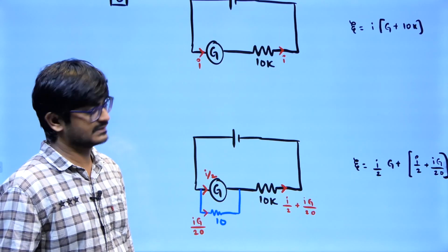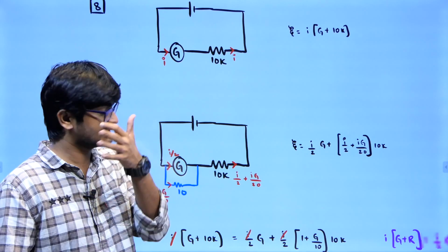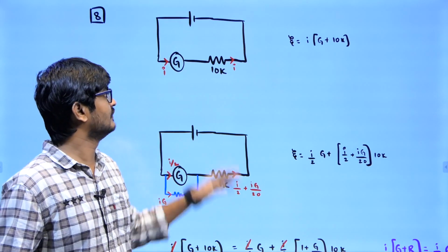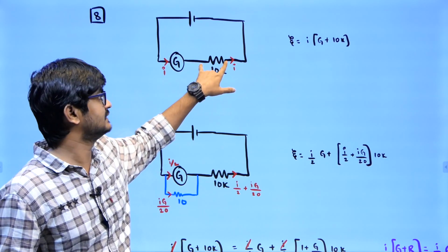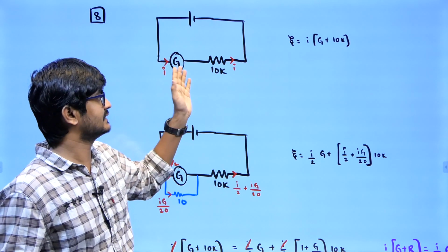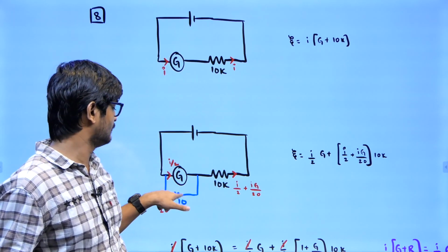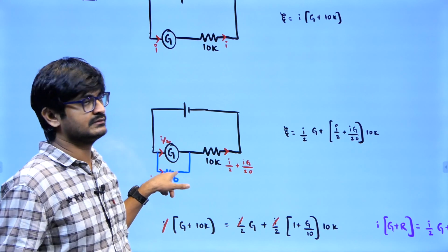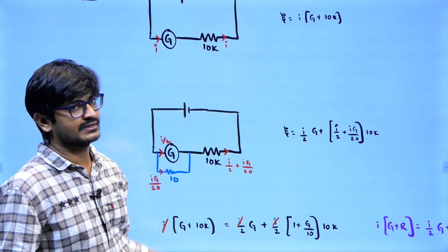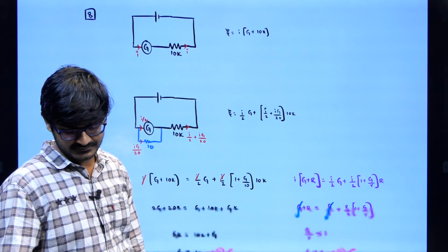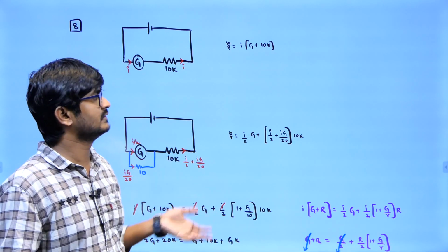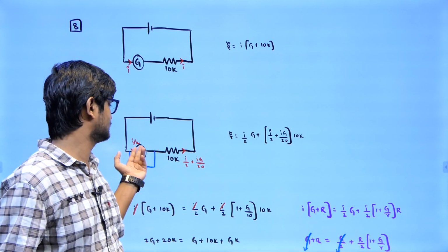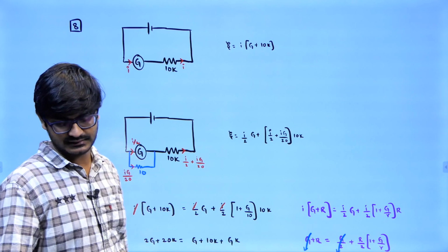So what is this method? In this method we are trying to find the resistance of the galvanometer. For that we connect some high resistance in series and see the deflection. Thereafter we vary this resistance so that half the current flows through it. Then we can conclude, without measuring anything, that the galvanometer resistance will be almost the same as this resistance.